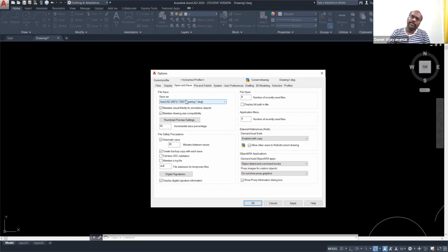Maybe you're thinking my AutoCAD or my application is wrong, and you don't know how to open it. It's not like that. It will show that your version is lower than that file's version. At that time you have to request them to downgrade their file so you can open it on your computer. Okay, so I want to go through fast.